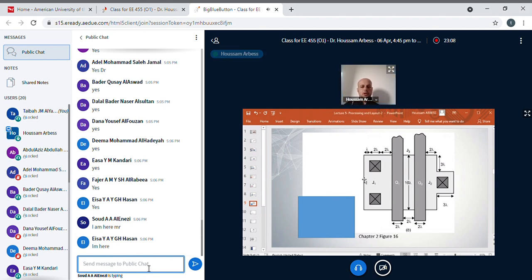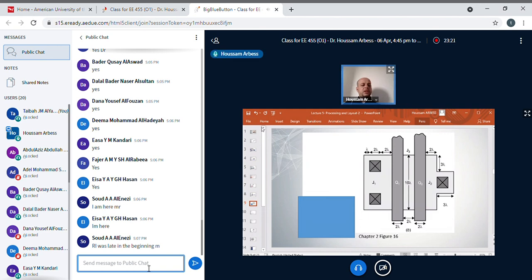Okay, let's go back to the circuit here. Did you get some idea about what devices you have here? Let me give you some sign. When I asked you to sketch the layout of the NMOS, I told you that the NMOS is like that, the most simple layout of the NMOS. Correct? Here you have N plus, here N plus, and here is polysilicon. Is that correct?